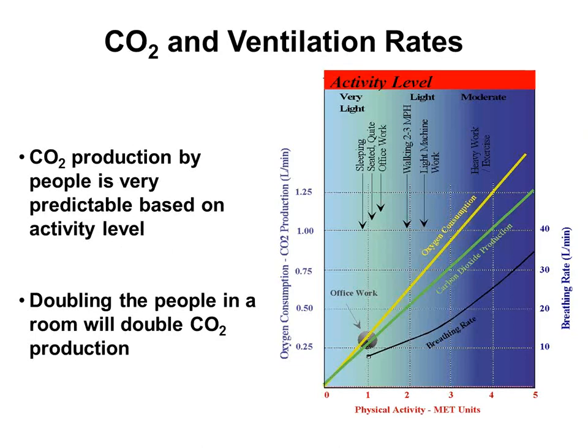I'm going to leave this as the last slide for today, and then we're going to pick up from this point. CO2 ventilation rates are a function of what you're doing. The more active you are, the more you are breathing, hence the more you are exhaling. Most of our check figures and rules of thumb come from classrooms and office buildings where people are seated and relatively calm, although a classroom might not be calm.